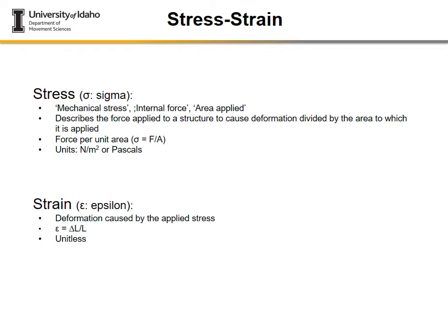And then you have what's on the x-axis, and this is strain, also known as deformation, or it's the quantity of deformation or change in length of that material as the load is being applied. And that's very important. So this deformation and change and strain that we're measuring is while the load is being applied. Okay, strain is a unitless number because it's a change in length divided by the original length. So it's not just how much change is happening, but it's literally, as you can see in this equation here, that delta or that triangle is change in length over original length. So if I had meters on top and meters on the bottom, they cancel each other out. So that's why it's unitless. So it's a very important component.